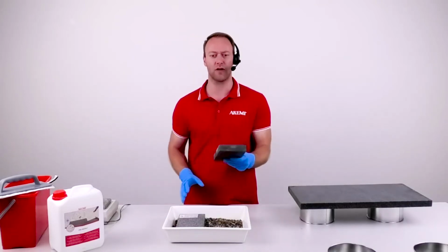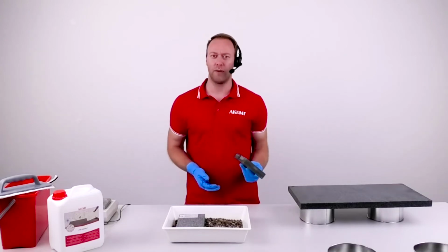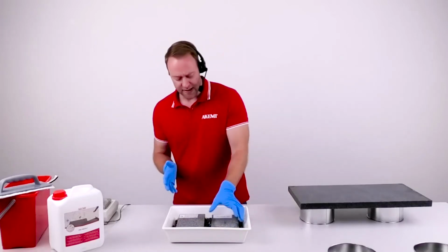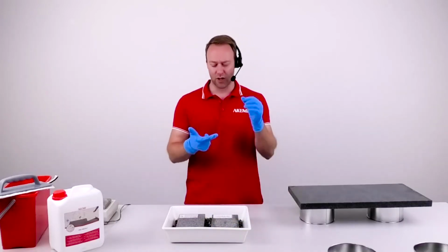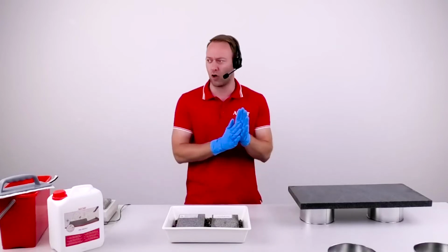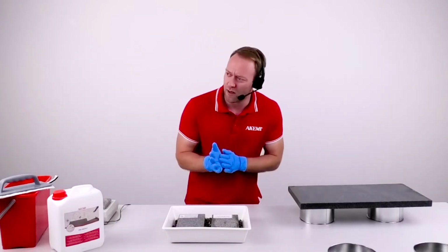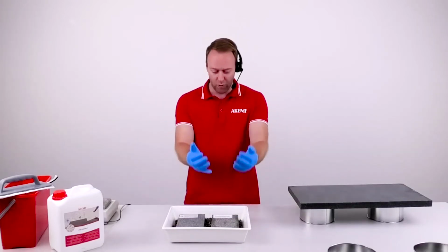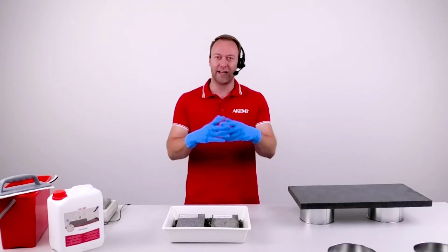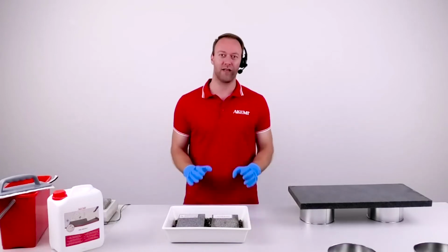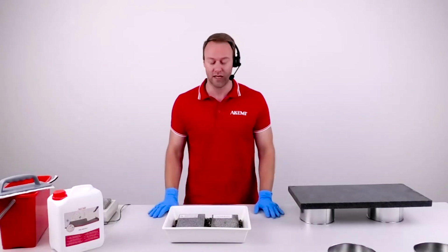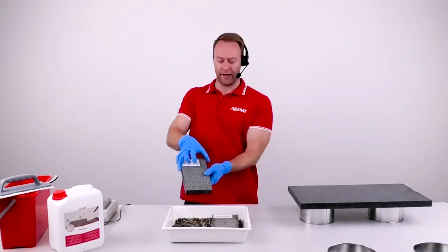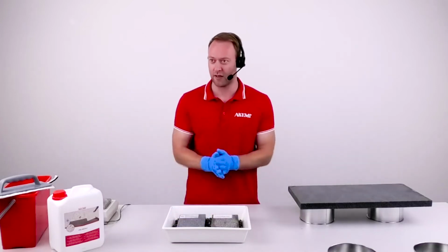Even if we put this stone now and dry it completely in an oven, these dark stains will stay because, as I said, in the water there are always some minerals, always some salts, always some lime scale dissolved, and it will push into the capillaries and then dry up and block the capillaries. Then you have the stains and they don't disappear anymore. So that's the problem. You can avoid it like this when you use the Pre-Protect.